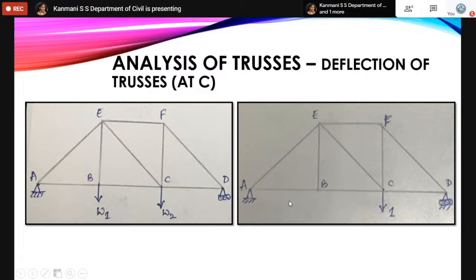If you consider this case at joint B, we have three members, out of which AB and BC are collinear to each other. So at joint B, member BE is 0, but in this case, when we have an external load exactly at joint B, since two members are collinear, the forces are directly transferable. So force in AB equals BC, and force in W1 equals BE in this case. These are simple tricks that will help you get the solution faster.